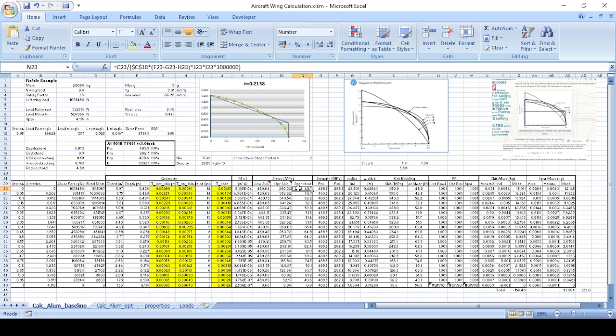If the thicknesses are the same, the shear stress in the spar is the number of spars times the height of the spar based on this chord, times this depth here, and times this thickness. Then I multiply by this area ratio, which is 0.785, because the spar is distributed over an oval section, so I've applied that. My shear stress also refers to this 0.785, and so it's my total shear force divided by my total area, which is my depth times my spar shear.